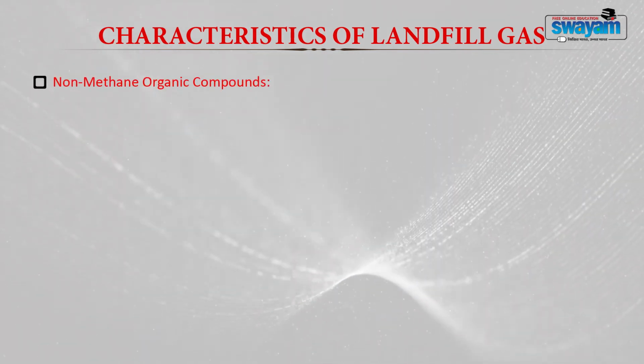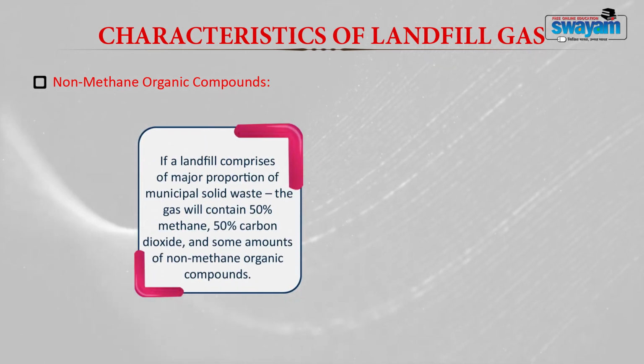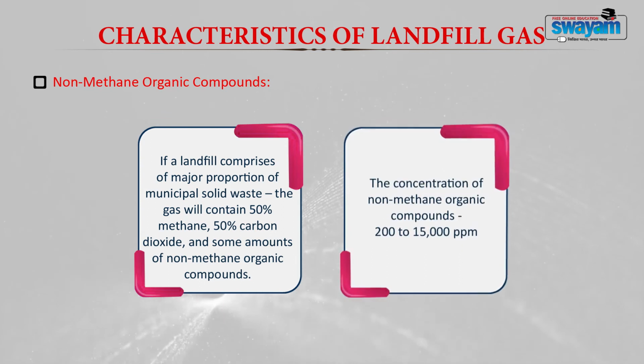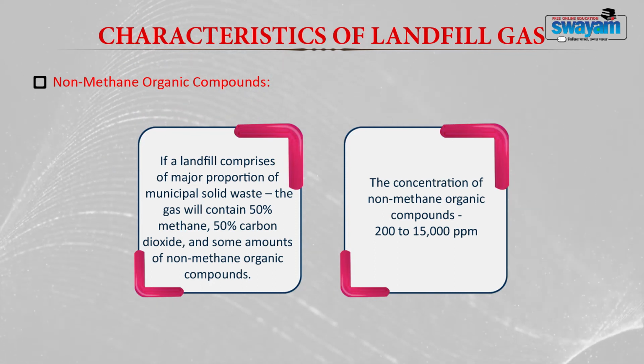The non-methane organic compounds contribute a major proportion if the waste present in the landfill is municipal solid waste. The gas will contain 50% methane, 50% carbon dioxide and some amount of non-methane organic compounds. The concentration of these compounds will generally vary from 200 to 15,000 milligrams per liter.